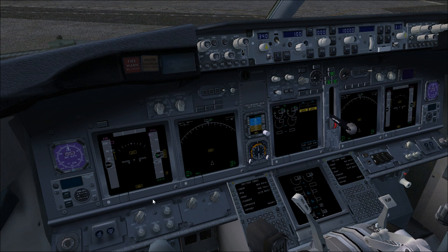In this case, as you can see, there is a landing altitude indication and no V-speeds indicated. This means that this information is not yet set up in our cockpit, so the PFD tells us this information is needed before the start of the flight. While the attitude flag, the vertical speed flag, the heading and the map heading, and the map indication show us that there is a failure of that information.